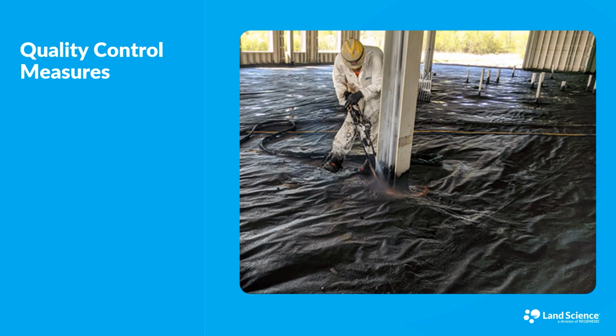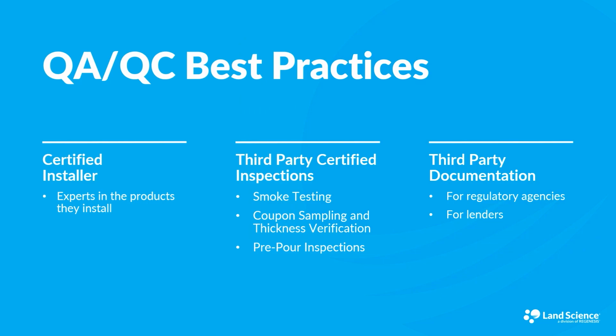Quality control assurance is a major facet of any vapor mitigation system installation. And these extra steps will help to ensure a great install and reduce future risk for the end user. For all spray applied barriers, there should be many layers of quality control assurance in place to confirm that the system is installed properly. This starts with the installation being completed by an applicator that has been certified and trained by the manufacturer. The installer will work together with the inspector to conduct thickness verification of the spray layers, as well as doing the smoke testing.